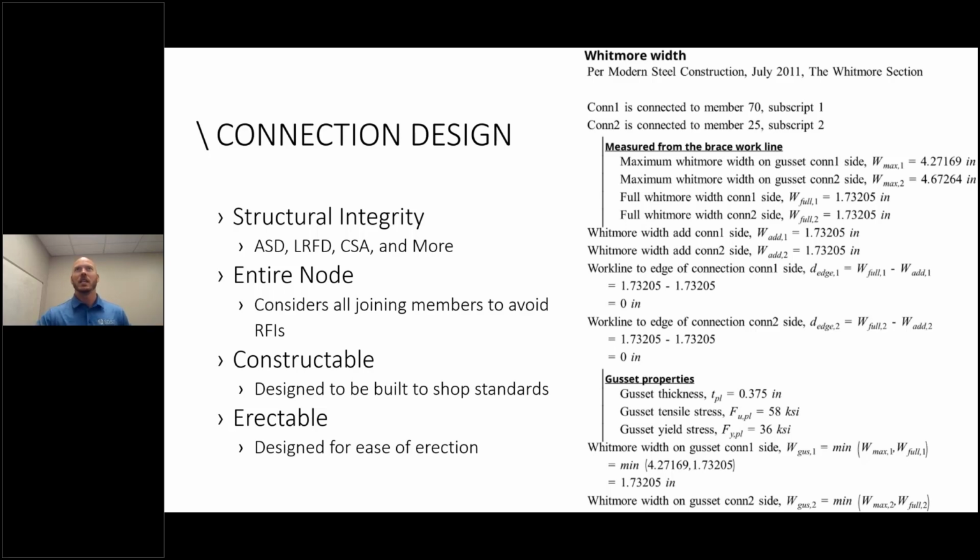You're going to see the hole rows, bolt sizes, plate thicknesses, all that, and you have to fill all that out, and then they'll give you a check and say, hey, this is good for this much load.